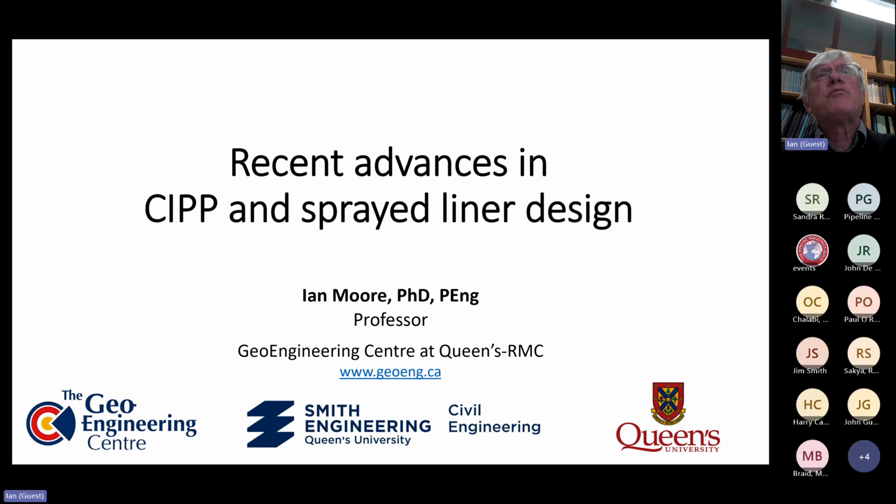That extrusion will produce a little annular bead of material, which you're absolutely right, will tend to lock in at those subsequent joints. And the research that we've done to date assumes that the friction or the slip that we get between the liner and the host pipe does not go past one of those locked-in conditions.